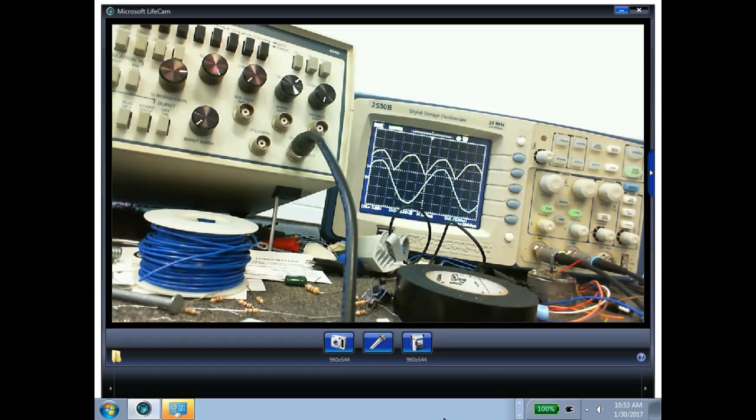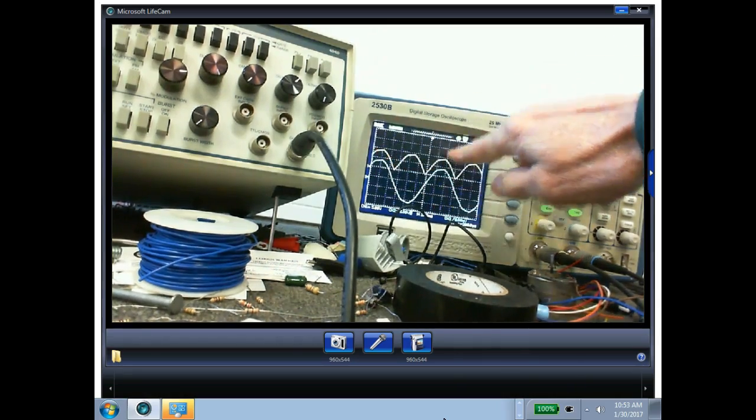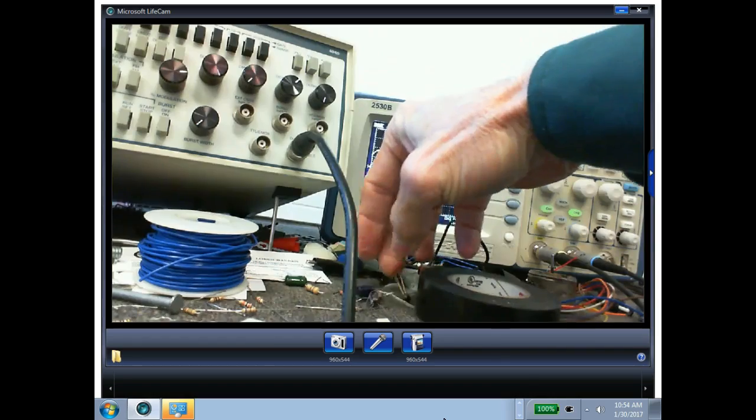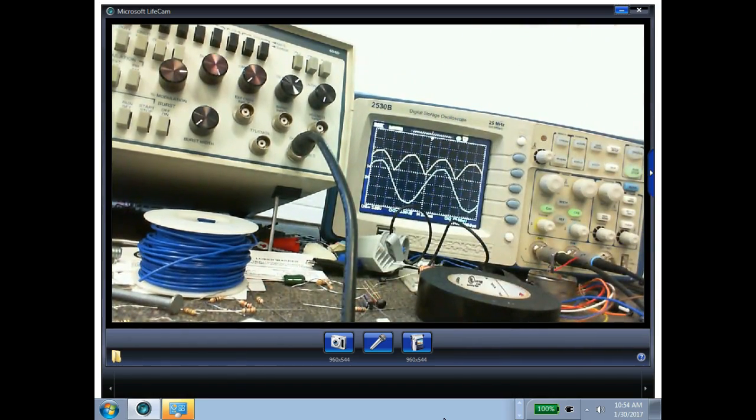Now later on, when we filter it, it's going to be more complicated when we start getting rid of these pulses. So our ultimate goal, of course, is to get rid of these pulses. So I'm going to use a device called a capacitor. I really make sure I get the right polarity. Now watch what happens here. Now that's DC. This is pulsating DC. That's DC. This is pulsating. And of course, that's what we're going to do.